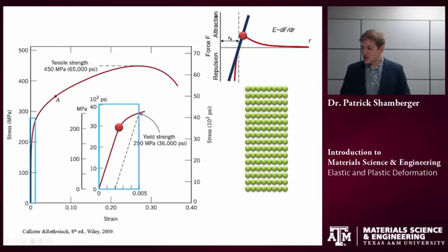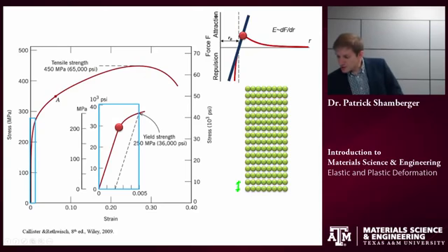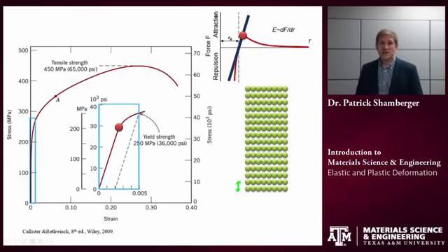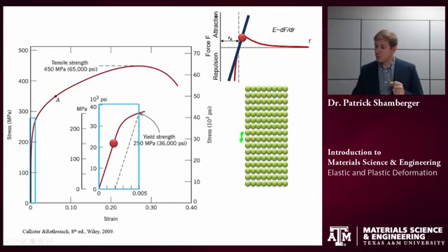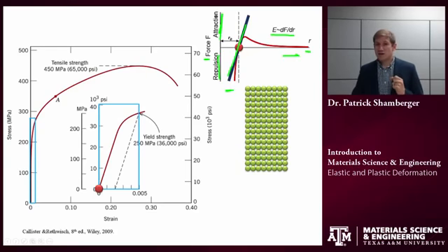And so in this case, the strain is going to be related to that increase in the interatomic separation. As long as I haven't gone past that yield point, when I decrease the stress back to zero, the atoms will all relax back to their equilibrium point. So when a sample is undergoing elastic deformation, you should think about atomic bonds stretching.